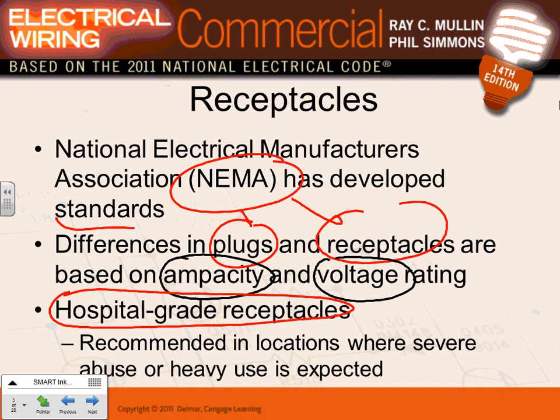Can I get you to understand there are two types of switches and receptacles? There's the cheap ones that we use for residential, and there's the expensive one that we use for spec, for commercial industrial. Everybody is cool with that? When you do the takeoff for me, you're going to use the ones called spec receptacles. These are the expensive ones.